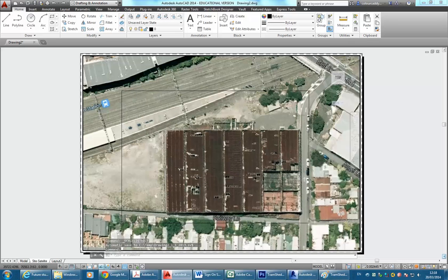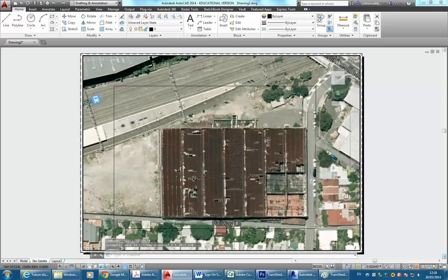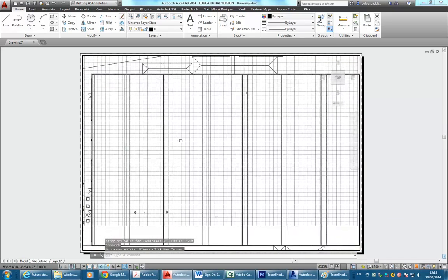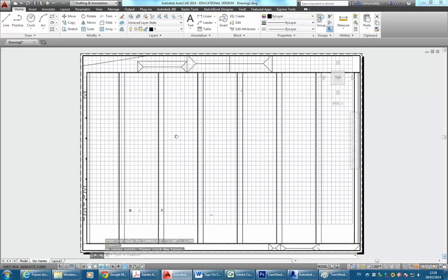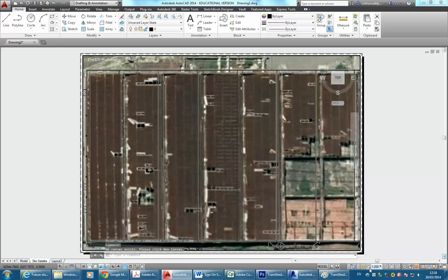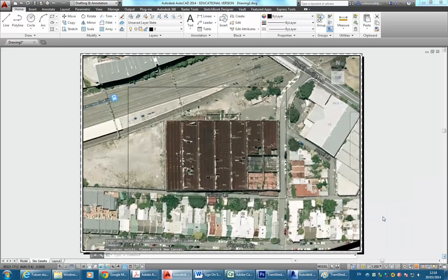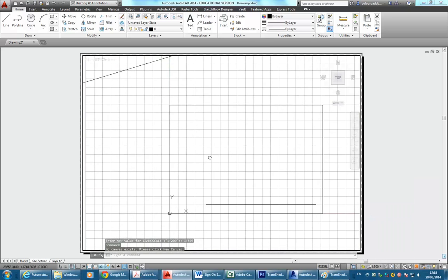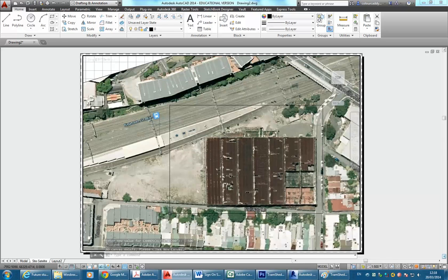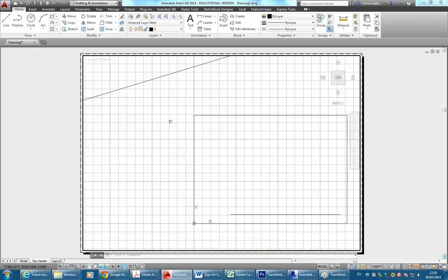Okay. So now if I go to this list, I've got those options. So 1 to 200, it's going to be good for the building actually. Maybe I can just get that. No, not quite at A3. But 1 to 500 should be, well, it is small and you shouldn't really use that scale for your final presentations, but for drawings at this stage, it's probably a good scale because you can print at A3.